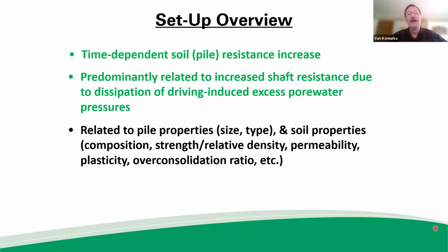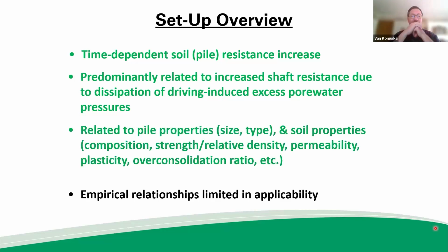So there are lots of factors that go into how setup is developed, what makes it happen and affects it. For those reasons, then, empirical relationships are limited in applicability. They aren't universally applicable. They have to be, by nature, conservative and have a large safety factor built in.